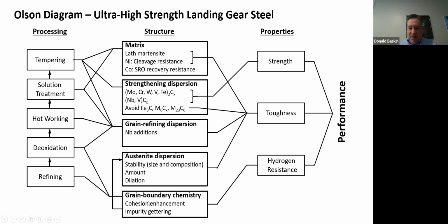And then finally, there's this issue of the system. The grain boundaries are another system. The grain boundary chemistry needs to be engineered. There's a failure mechanism called hydrogen embrittlement, which I'm not sure if you guys have gotten into in some of your undergraduate classes, but hydrogen embrittlement is a rather nasty little problem. I've experienced it several times myself.